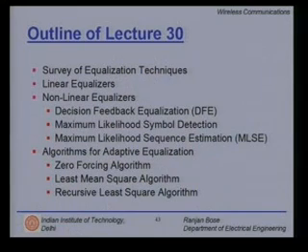We will start with a brief survey of equalization techniques, followed by a study of linear equalizers. Then we will move into the domain of nonlinear equalizers. We will look at the decision feedback equalizer or DFE, then the maximum likelihood symbol detection, and finally the maximum likelihood sequence estimation. Finally, we will talk about algorithms for adaptive equalization. The three important algorithms that we will study are the zero forcing, the least mean square or LMS, and finally the recursive least square algorithm. So this is the brief outline for today's talk.